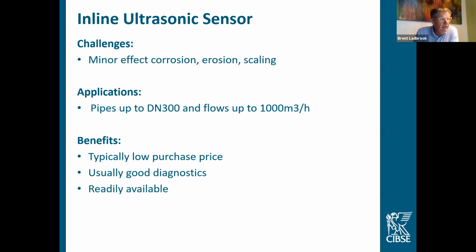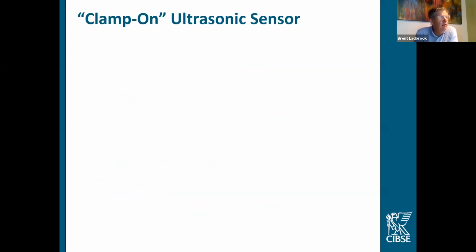There's a number of manufacturers out there, some with more features, advantages and benefits than others. Typically a very good turn down ratio. So this is the number between our design permanent flow rate QP and our QI, our minimum guaranteed accuracy, typically 100 to 1 or better. And if we took QS to QI, that becomes a much, much larger number. Turn down ratio is 100 to 1 typically, often available up to 250 or even higher as well by special order.